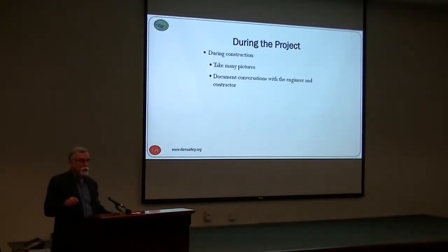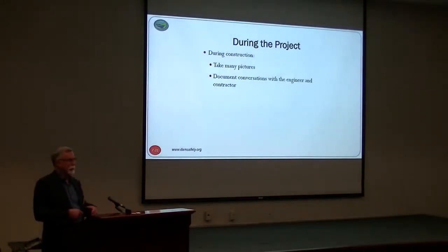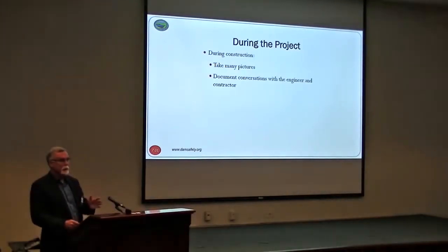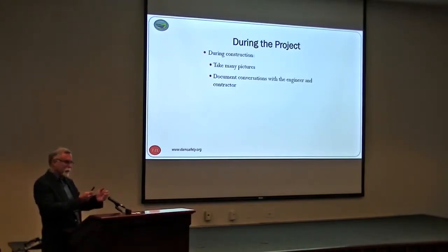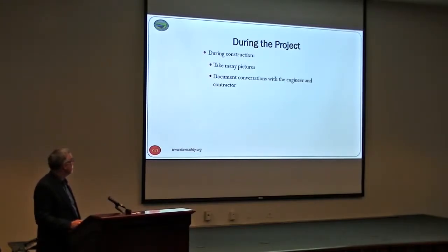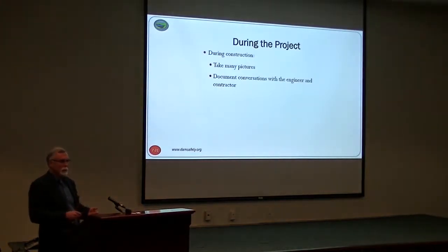The engineer should, and you, now with digital cameras, it's easy to take pictures. Take hundreds of pictures and keep them, because if there's a problem down the road, you can look back and say, now I remember over on this side of the dam we found a certain type of rock that was highly fractured or something. So take a lot of pictures and keep them. And then, for your sake, if you have a conversation with the engineer or a contractor, document it. Keep a field book of exactly what you were told and why you were told a certain thing.